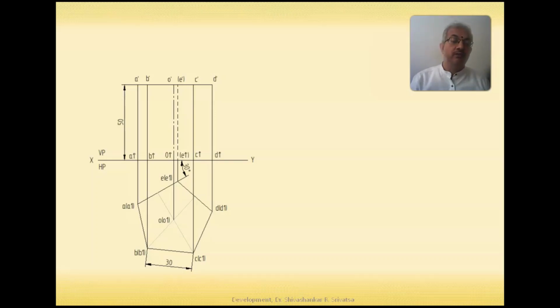Now first task, once we draw the front view and top view of the solid in the given position, we will have to do the basic development. This is a prism, so you would be making use of the parallel line development, and you would reproduce the 5 rectangular faces of the prism in their true shape. I will be making use of these two parallel lines in order to develop 5 rectangular faces. So this is our first rectangular face.